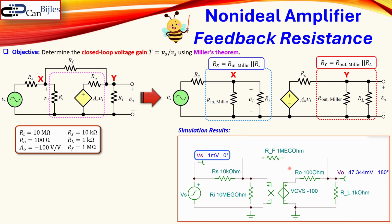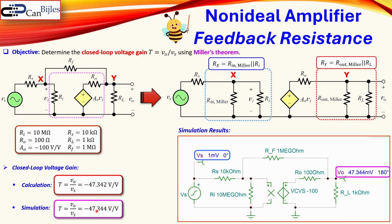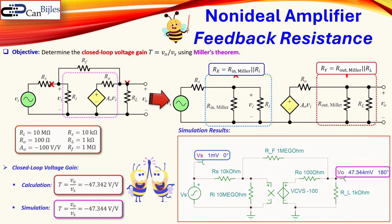That means it's already inverted, so that is a minus sign in our result. And it has a gain of this value divided by that. And in our calculations we had determined that the voltage gain was minus 47.34. And here from the simulations we do again this value divided by the input, and you will have minus 47.344. Now, well, this is almost the same, so we can say this is nice.